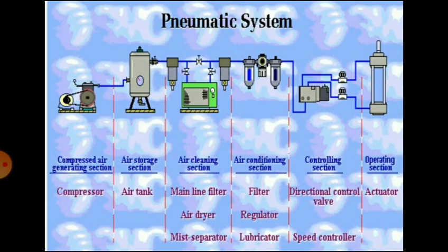Now pneumatics, the second branch of fluid power, utilizes the freely available air as the working medium, that is, to transmit power from its source to destination. The major difference is that air is compressed and under pressure at the time it is delivered, even if there is no load on the system. Whereas in hydraulics, pressure is developed only due to the presence of load, that is, resistance to flow.